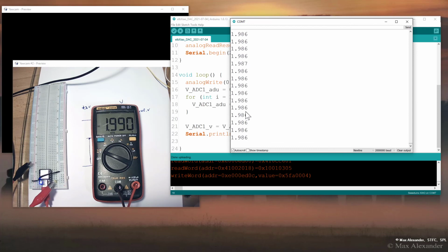That's less than 0.2%. So you can see the absolute accuracy of the ADC using this little trick of scaling it with the voltage on the 3.3 volt rail that we actually measure. You can see that's giving us better than 0.5% absolute accuracy. That's what we want. Okay, and now we're ready to go to the next step.